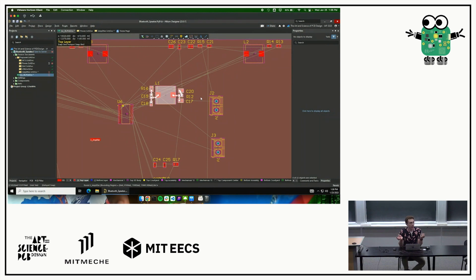This looks a lot like the board that we gave you, because this is kind of the way that Texas Instruments wants this chip to be routed. When you start looking at chips that do a lot of stuff all at once and have some high complexity associated with them, usually they give you a guide for how you actually route the part. Sometimes that's in the data sheet. Sometimes if they need more explanation for it, they'll make another document called an application note, or an app note, that will tell you the specifics of what you should be doing.